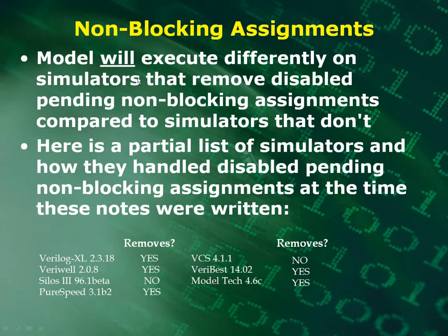So in other words, your model will execute differently on simulators that remove disabled pending non-blocking assignments compared to those that don't. And at the time that I originally did this, these were some of the simulators and how they reacted to it. So you may want to check your particular simulator if you, for some reason, do this.